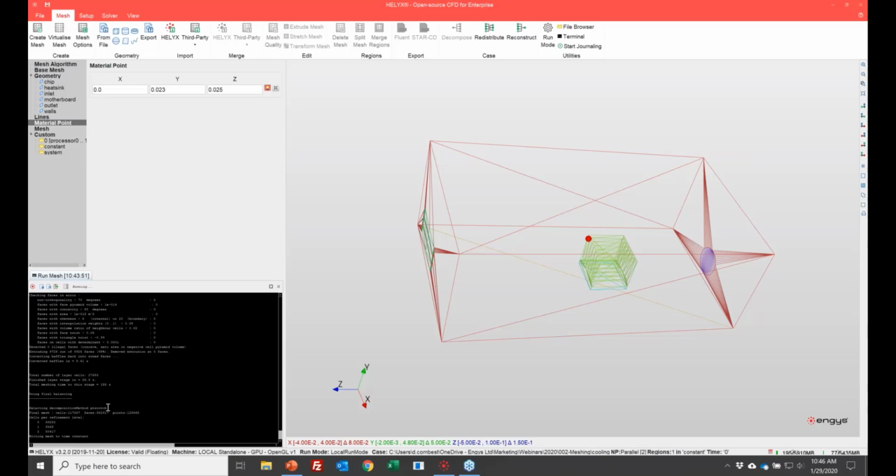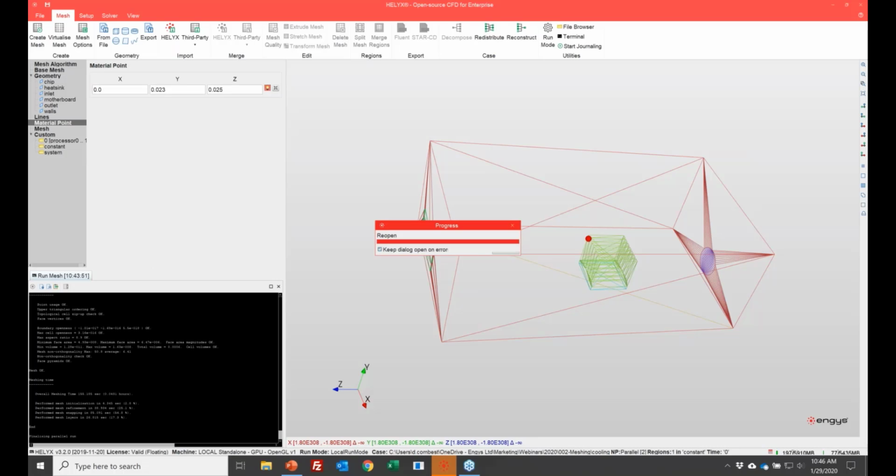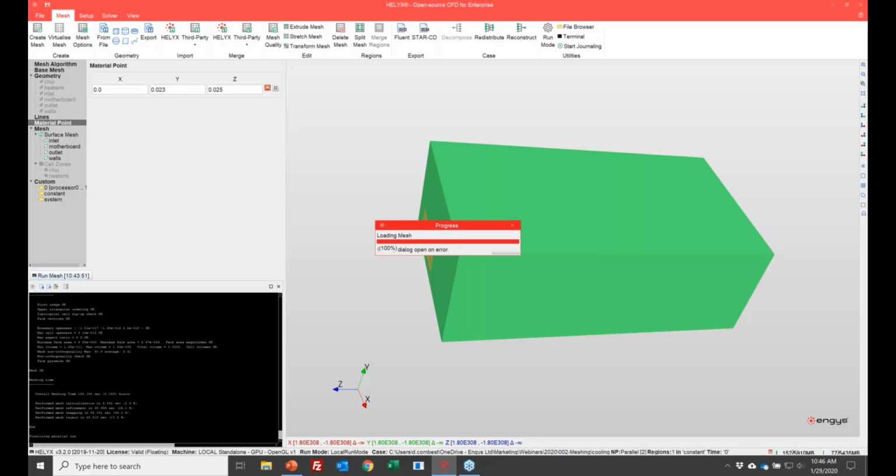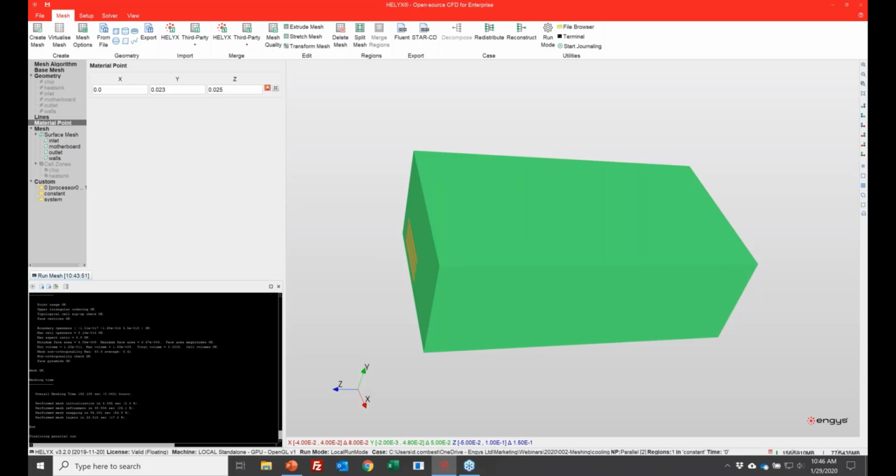Right, doing final load balance. So again, my original points: you need a mesher that enables you to move with agility, to be able to set these things quickly, and then also scale well in parallel. This mesher automatically redistributes to the number of processors to try to equalize the number of cells on each processor and also minimize the number of faces between.